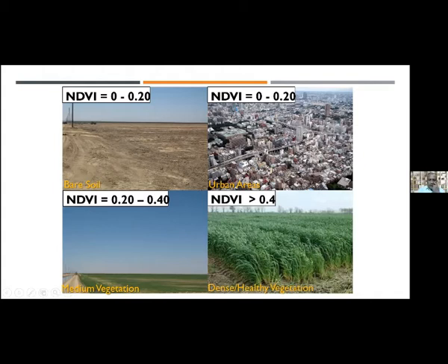But again, as you process the images, as you develop these NDVIs, you will get more ideas. So this is just for reference purposes. And then NDVI greater than 0.4 indicates good, healthy, and dense vegetation. Okay, with a full cover. Okay, so that's good, and you can take that as a reference. But again, not exact values. Values will change.